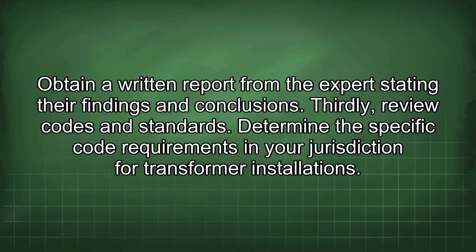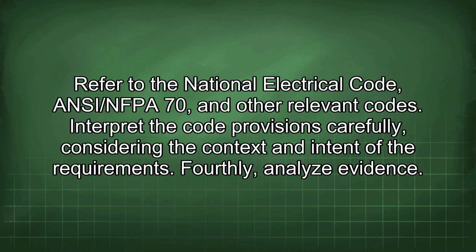Thirdly, review codes and standards. Determine the specific code requirements in your jurisdiction for transformer installations. Refer to the National Electrical Code, ANSI/NFPA 70, and other relevant codes. Interpret the code provisions carefully, considering the context and intent of the requirement.